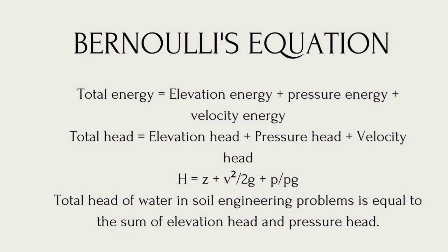This principle is named after the Swiss mathematician and physicist Daniel Bernoulli, who published it in his book Hydrodynamica in 1738. Although Bernoulli deduced that pressure decreases when the flow speed increases, the principle is only applicable for isentropic flows, when the effects of irreversible processes and non-adiabatic processes are small and can be neglected.